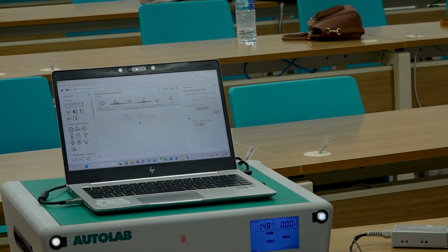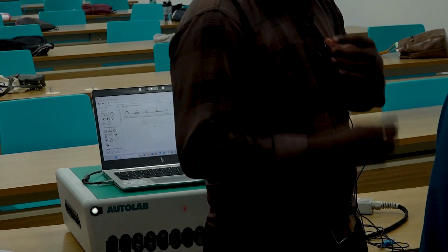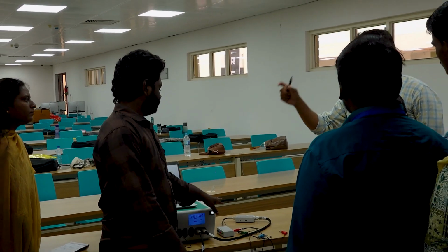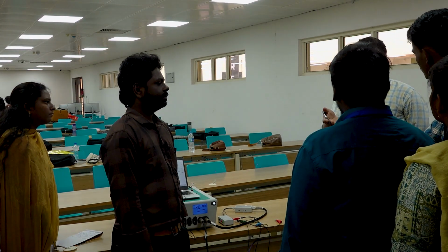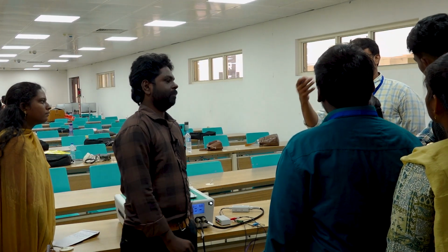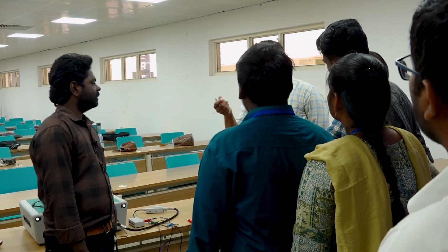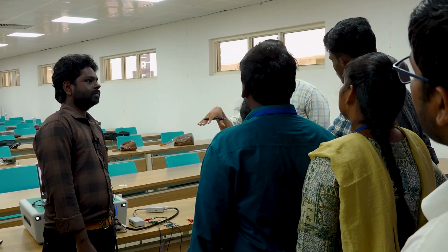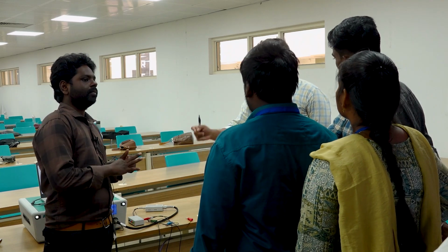Any electrochemical cell, like a solar cell or supercapacitor, whatever you are fabricating, can be converted into an electronic circuit like a capacitor, resistance and impedance. Whenever you are going to do research on solar cells and publish any new cell or new combination of cells, the experts will definitely ask what the equivalent circuit of your cell is. Normally that is understood through this EIS analysis.